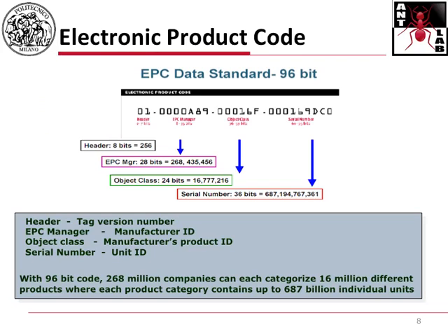Just like for IP addresses or MAC addresses, the format of IDs which are stored in RFID systems is semi-standard. So it's standardized, let's say. The reference format of these IDs is called EPC, which stands for Electronic Product Code, which specifies a format of what can be stored, or what should be stored, in any RFID device.